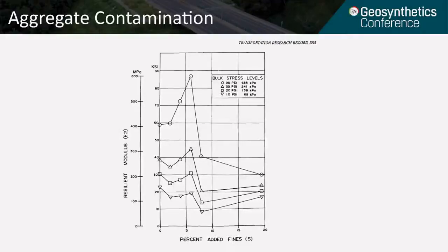So we'll actually look at this a little bit in a study later. Just note that even just a small amount of fines contamination can have a significant impact on the modulus and the bearing capacity of the aggregate layer.